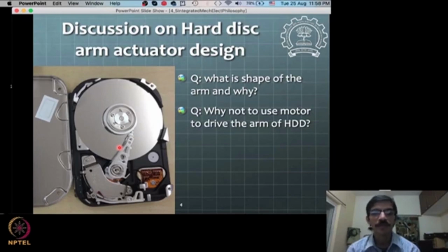That is a more rigorous or stronger constraint, which typically gives you a design which has much lesser stress than what will cause the system to fail. So keep in mind that when we design mechanical systems, they are designed more for the deformation than for the stress.